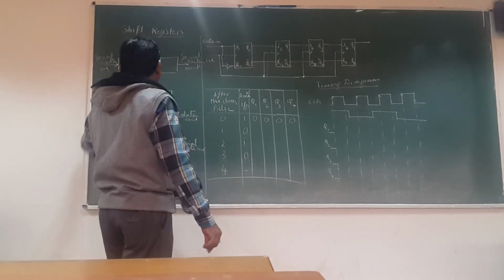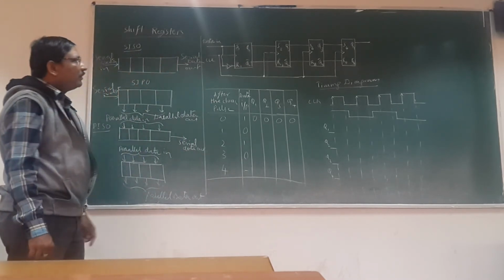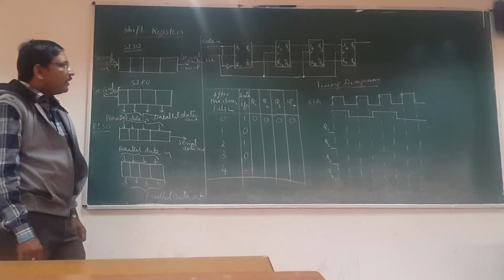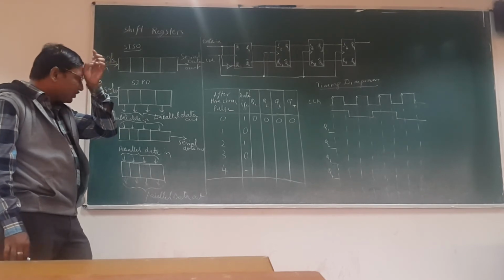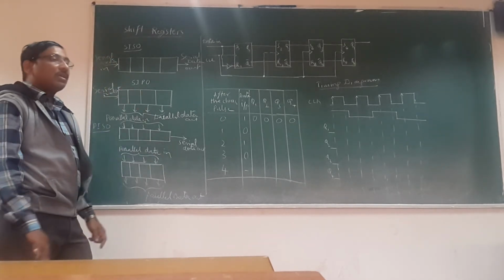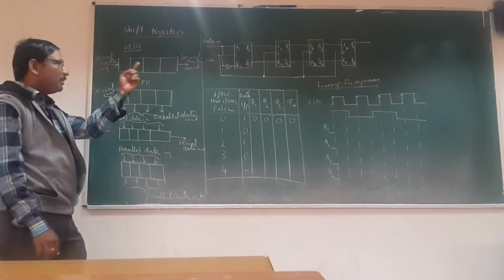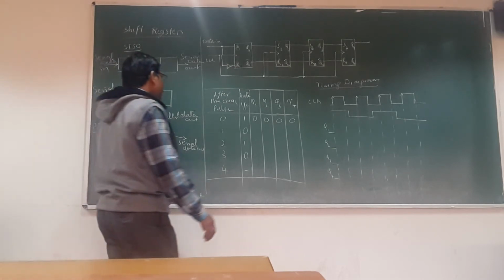So here is the diagram. These shift registers are going to be built by using the flip-flops that we discussed so far. For a shift register, most of the time we use either SR flip-flops or D flip-flops. You can use either SR or D. So this is a diagram using the SR flip-flops with a small modification.